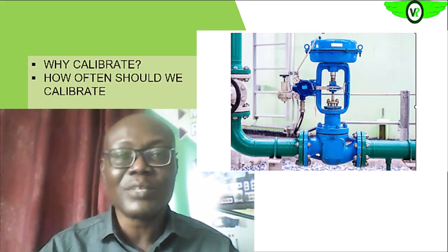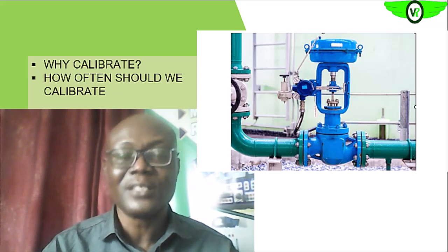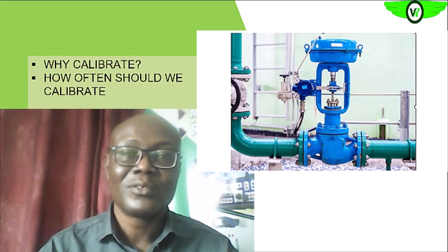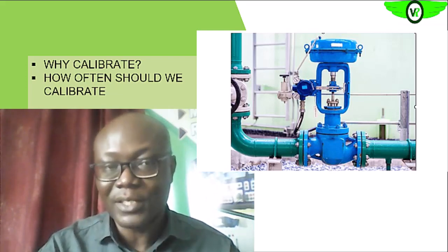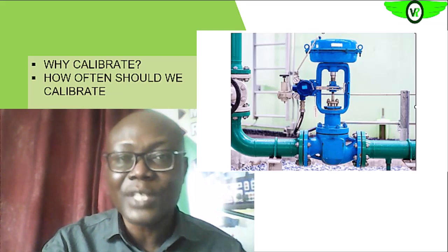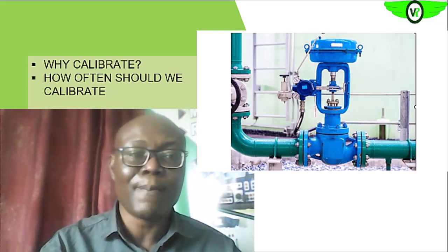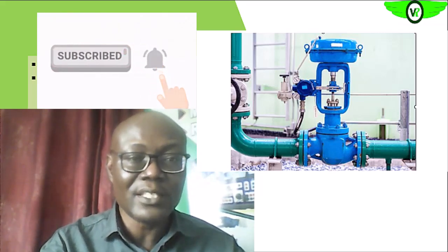Some instruments are calibrated monthly, some annually, some biannually, and some take some years before they are calibrated. So it depends on the process condition it is subjected to and the usage of that instrument.